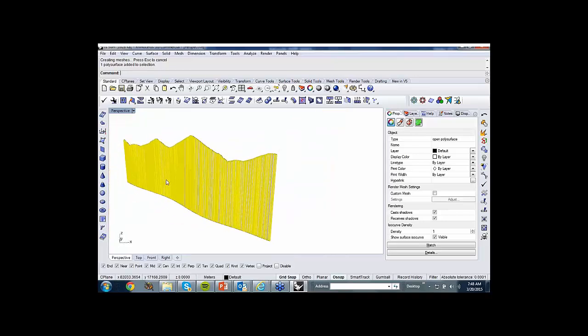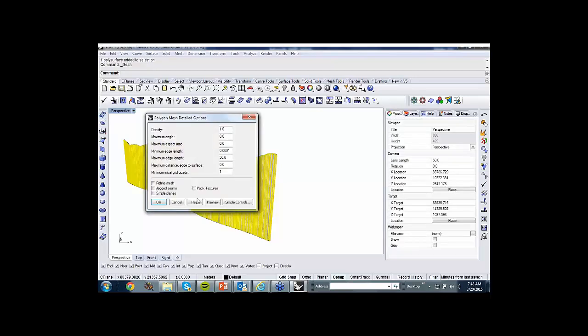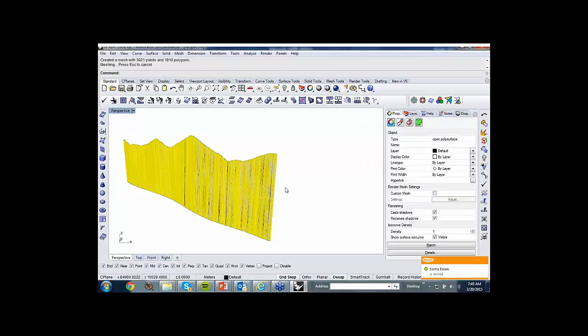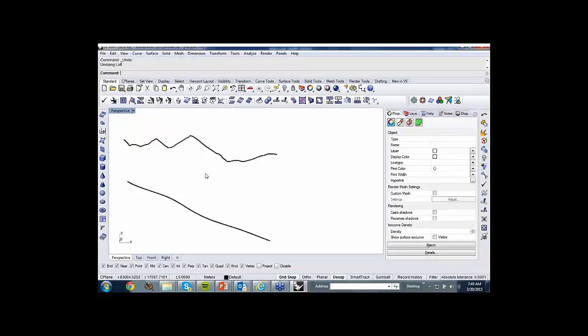It has a lot of tiny grid points, and once you mesh that, I can experiment with that right away. Using simple mesh, you're going to get a mesh that is a lot of skinny stuff. This is asking for trouble right away. So what I'm going to do is go back and say no, I don't want that.